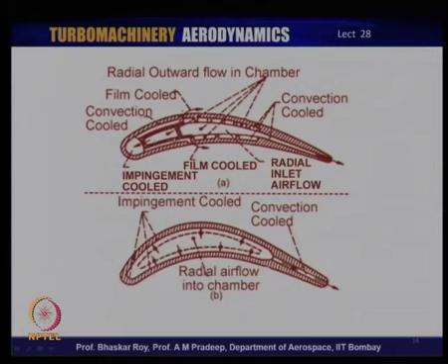Whereas, here we have holes. So, impingement cooling is used at the leading edge to cool the leading edge, which as we mentioned can be a hot spot, and then of course, it cools the other surfaces through the internal cooling system, and then again here we allow the air to come out through the trailing edge, in the process cooling the trailing edge also. You remember after it cools the internal surfaces, the cooling air itself gets a little hot. However, as we have just seen, the trailing edge is really very hot, and compared to that, this internal air is still cold. So, all you require is air that is substantially colder than the outer hot gas, and it still can do a little bit of cooling. You do not need very cold air here, you need air that is a little colder than what is outside.